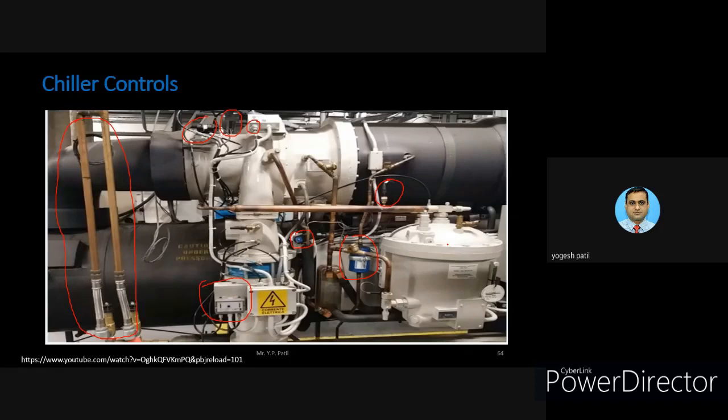If flow sensors give the signal to the controller, yes, water is present, then the things will get turned on. We can say that is start operation. The chiller also needs to know the temperature of the fluid of the chilled water loops. So temperature is also one of the important parameters that the chiller needs to know, for both the loops, in the evaporator as well as in the condenser. And based on their measurement, the next action will take place.